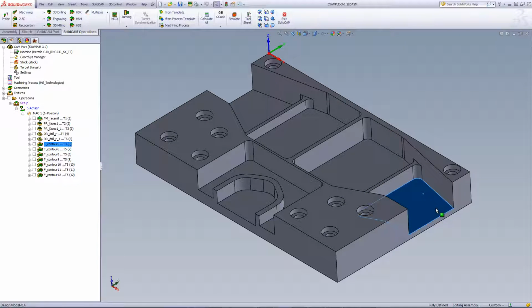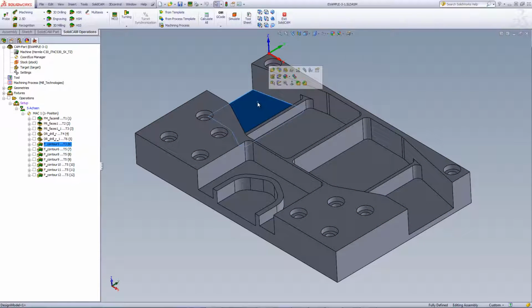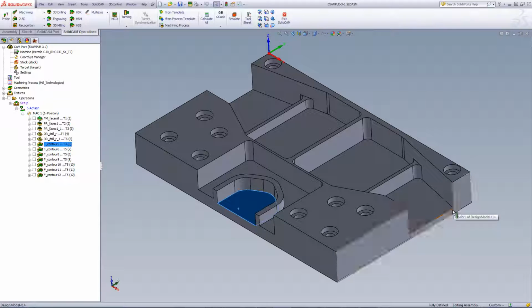We also have these floors that have this edge to be machined out here, as well as on the floor on this side, and these floors over here, all of them being at different heights. But not only that, in this particular case, as well as in these cases over here, the tool cannot go all the way up to the wall. It can only use part of that chain over there, as well as these areas over here. So let's take a quick look at some of the operations I've done.